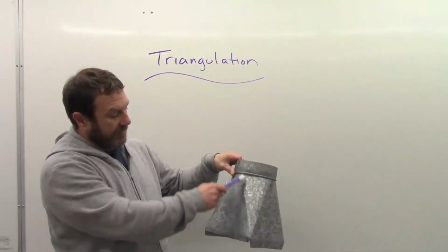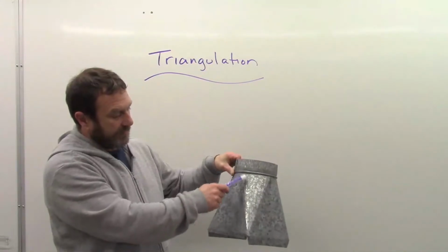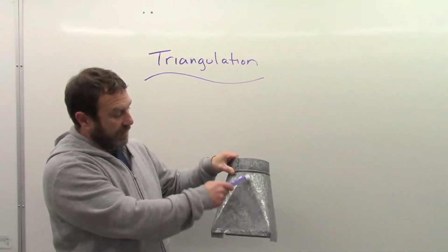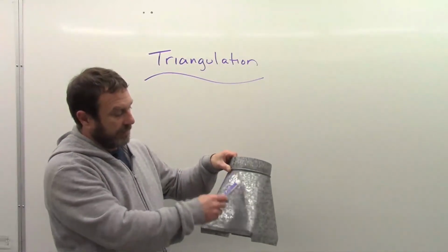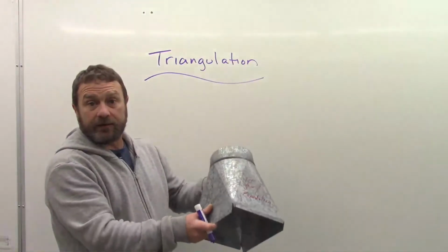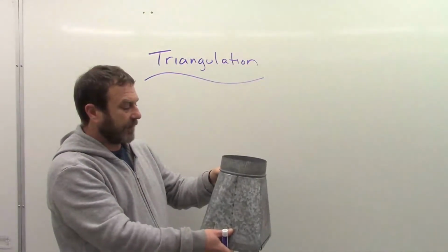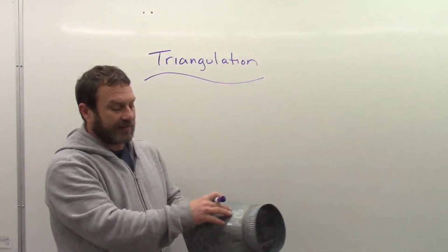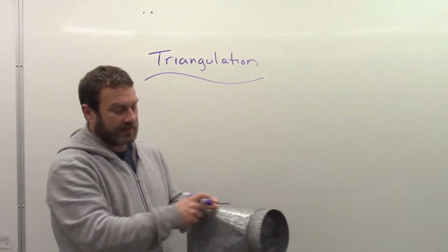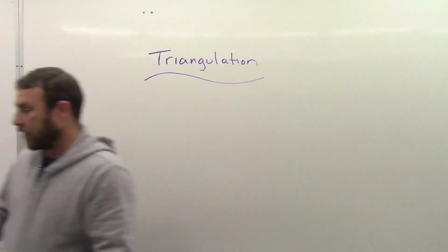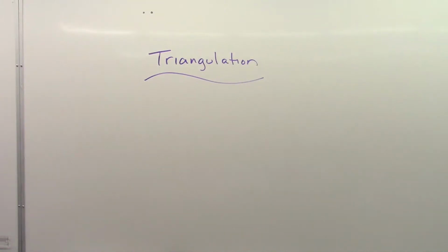And if we really look at those bends, it's a whole bunch of different little triangles packed one on top of each other. And we started with this large triangle here, triangle after triangle after triangle. We make the pattern. Okay, that's our triangulation layout. But it's finding the true length of these lines, these element lines, that's the hard part. And that's where we struggle a little bit with triangulation.